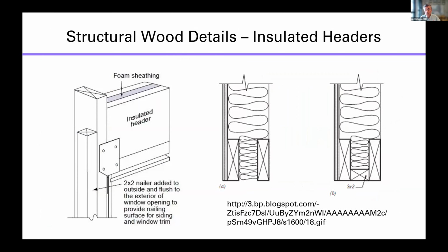Quickly now, insulated headers. They come and go in terms of availability from manufacturers. You can build them yourself. There's no reason to use a solid wood header when you don't need it structurally. There are different options to develop both field applied and factory manufactured insulated headers.